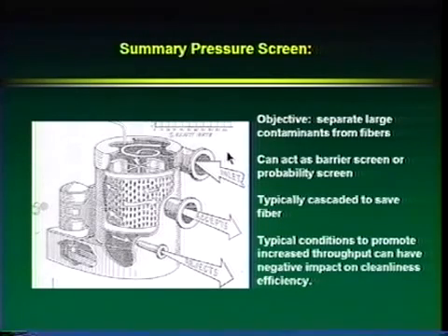So we know that in our case we have this rotor, and that helps us improve our throughput. But actually that small gap between our rotor and our faceplate can break particles or actually cause them to pass through. So that's one case where we're improving throughput, but there's a slight disadvantage in that we can break particles and allow them to pass through from the action in that little gap of that foil.